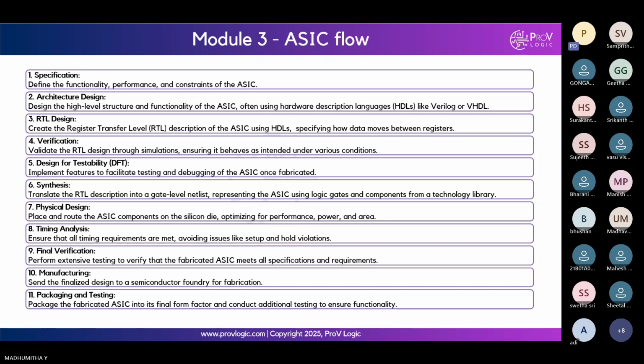The fourth step is verification. Verification means we will verify if the code that was written by the RTL engineers is correct or not. So all the debugging of the code will happen there. They will use some simulation tools where they will run the RTL which they have developed, and they will find if there are any errors or warnings which the design engineer should work on, or if the design has passed. So all of this information we will be getting when we are doing the RTL verification.